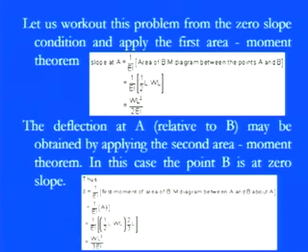So you see here we have a triangular element. In that, we can simply calculate the area as we calculated, which is equal to 1 by 2 the distance, this is L, into the height, that is WL. Then in this AY, the Y bar is the location of the centroid from that point. Since it is a uniform triangular part, it is 2/3 of the distance. So by keeping those values here, we have 1 by EI into half of L into WL into 2/3 of L. So by keeping those values, we have WL cube by 3 EI.